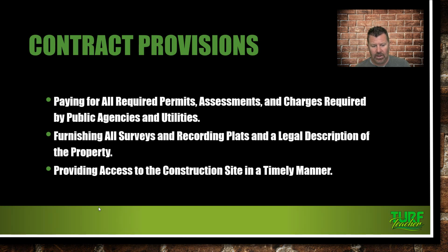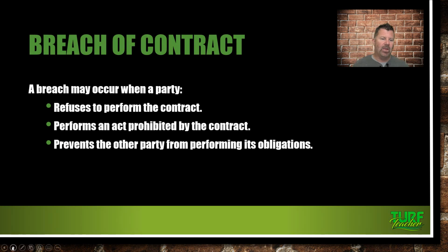Furnishing all surveys and recording plats and a legal description of the property, and then providing access to the construction site in a timely manner. However, those specifications may say that the landscape contractor is to provide silt fencing around the entire property and install tree protection fencing and install riprap at the construction site driveway. That's why you need to read those specs, guys, because sometimes that is the landscape contractor's responsibility. They kind of sneak it in there and get you to do it free.